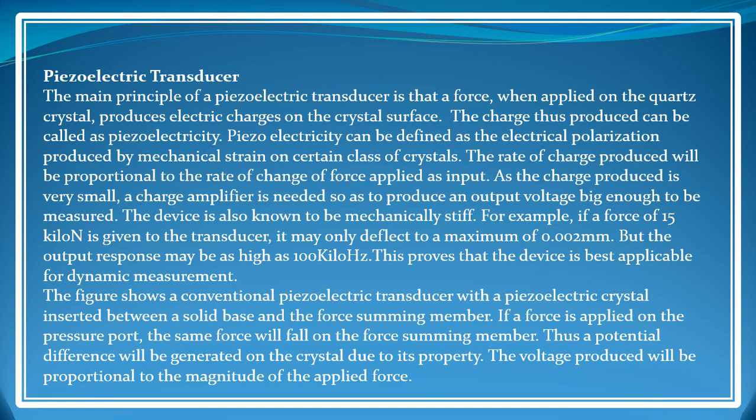Piezoelectricity can be defined as the electrical polarization produced by mechanical strain on a certain class of crystal. The rate of charge produced will be proportional to the rate of change of force applied as input. As the charge produced is very small, a charge amplifier is needed so as to produce an output voltage big enough to be measured.